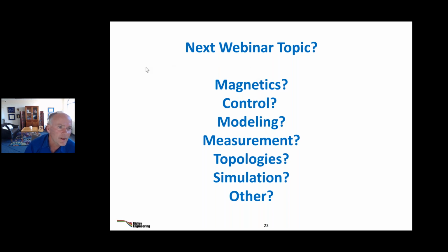Ron, how do you bring LTspice waveforms back to RidleyWorks? That's in the manual. Basically, you have to save the file as a text file, go into RidleyWorks, click import, and it brings them in. So that's easy to do.